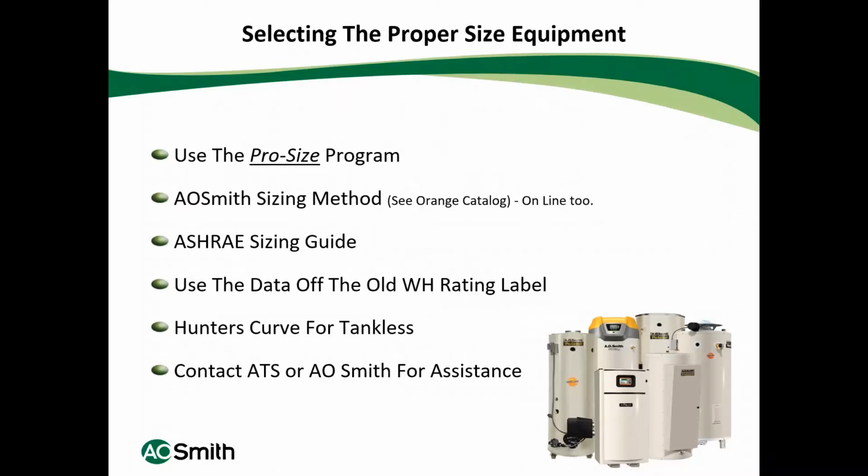Every water heater has a label on the side of the boiler, the water heater, with what storage and recovery data is there. So sometimes replacing like for like is a pretty good method, providing your client has never had issues with the system in the past.